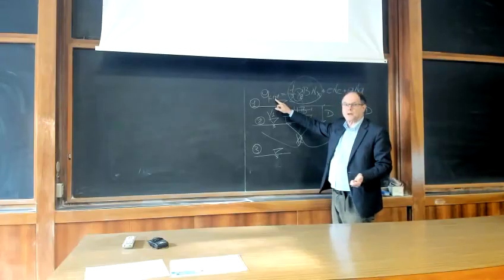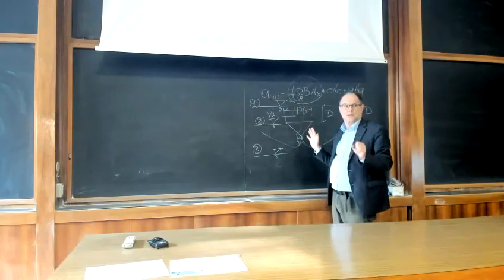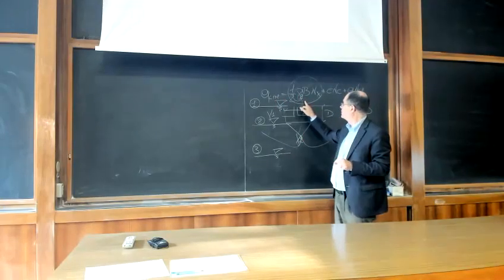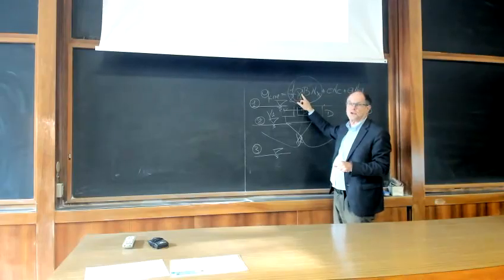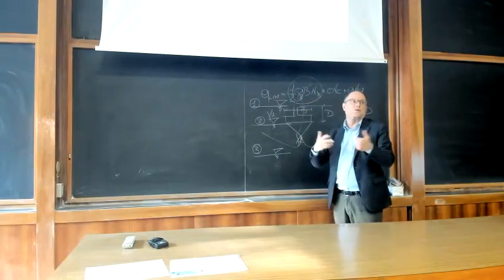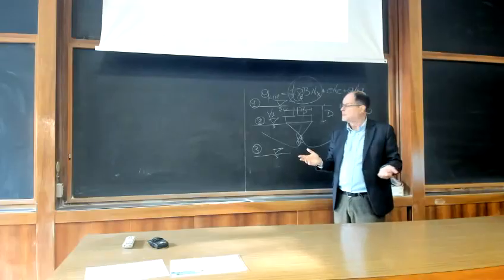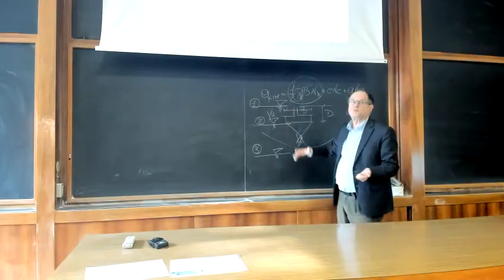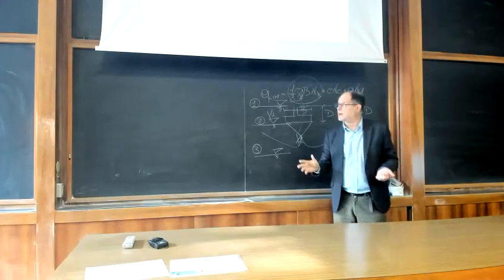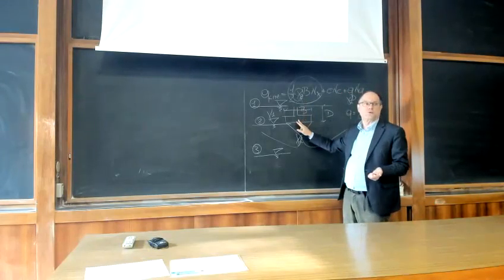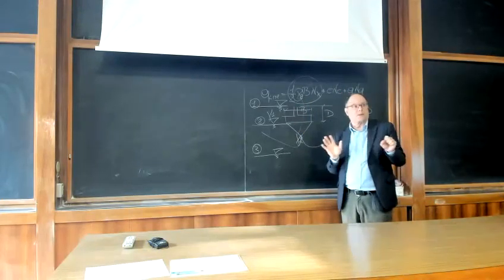Your limit pressure, everything else being equal, will drop because you have gamma dash instead of gamma saturated or the natural unit weight. So the groundwater oscillation can affect the capacity of your footing without you doing anything.